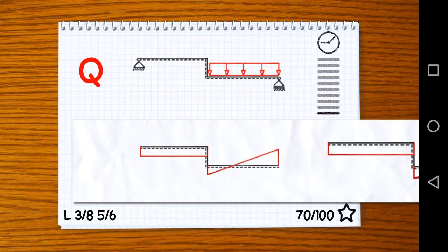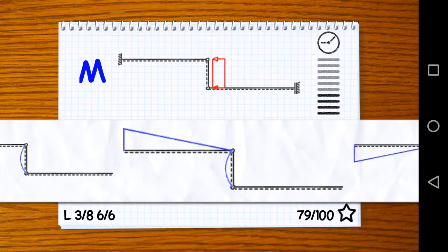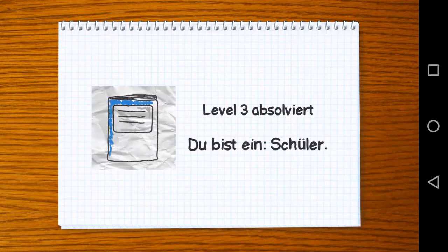It's going to be a little bit tricky just doing it right now. Look, that vertical part here looks like a bar, right? A simple bar that should normally not have any bending moment, but in this case we have a distributed load perpendicular to it. That's why we're going to have a bending moment there. And the other side, what's going to happen with the rest? Basically nothing. If you do the sum of the forces in the vertical direction, there's none. In the horizontal direction, there's none. So only this one is correct, and that's it.